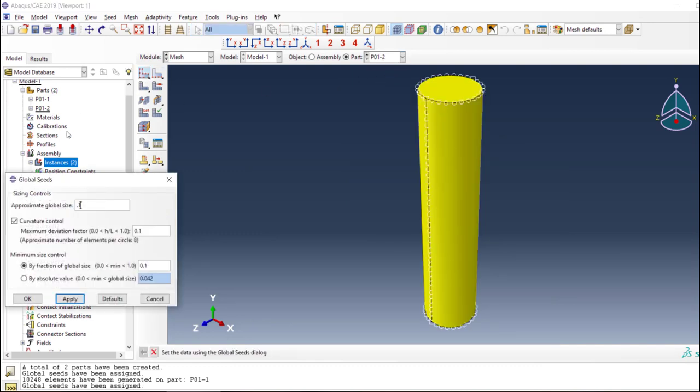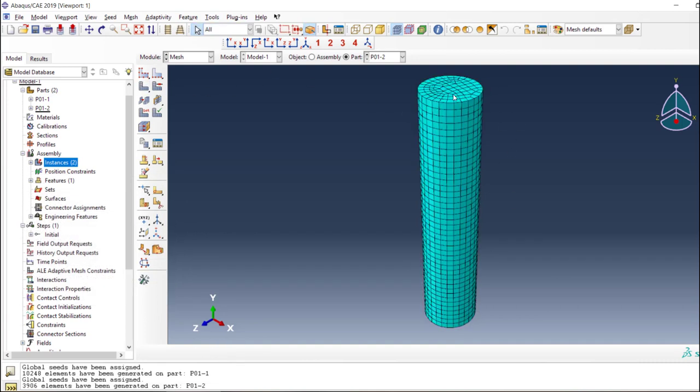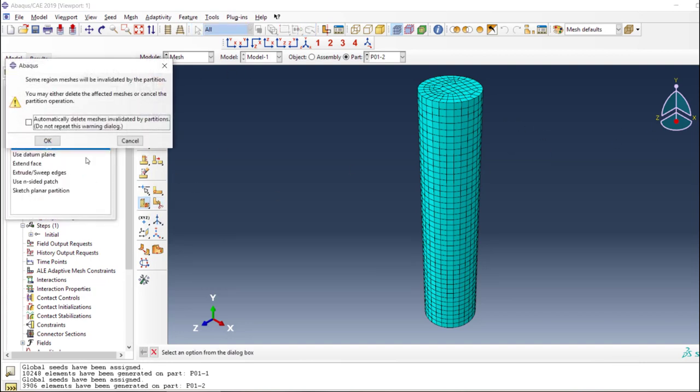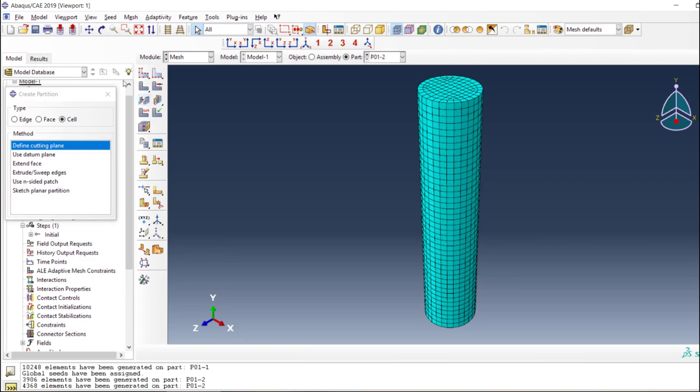But you see that now it's showing yellow because it can still be split into different parts and cells, and we can create a better mesh. Okay, now let's split again. This is a feature that you cannot have in Ansys. Now it's green, now it's all good.